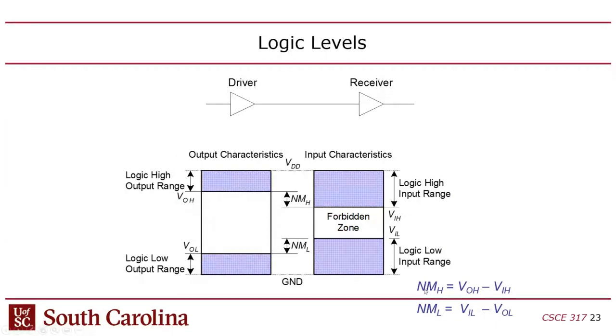Yes, those are written out right here. Noise margin high is VOH minus VIH. Noise margin low is VIL minus VOL. And that's how much noise you can have affecting the wire. Now you might say, wait a second, are you talking just about crosstalk? No, there are other sources of noise as well. Crosstalk is a major one, but there's also power supply noise. When these transistors switch, the voltage supply, VDD, is not stable. It's noisy. It's got noise on it, like static.